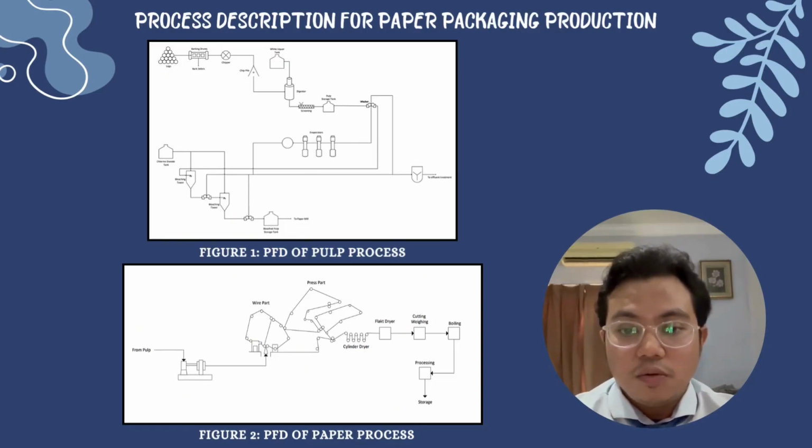Next, the wood chips go into the digester, where they are cooked at a temperature of 200 degrees Celsius and a pressure of 9.6 atm. The wood chips are dissolved with a caustic solution called white liquor. White liquor is a mixture of water, sodium hydroxide, and sodium sulfide. After dissolving, the remaining white liquor turns into black liquor. The resulting product removed from the digester is called pulp.